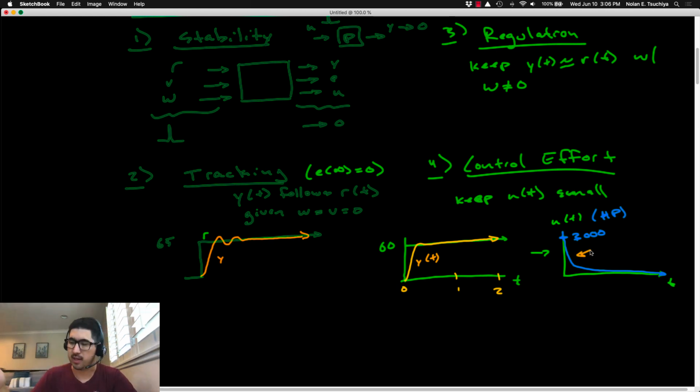In other words, even though theoretically it's possible to design a control system that takes a vehicle from 0 to 60 in under 1 second, the theoretical basis for that would be to provide upwards of 3,000 horsepower for that initial acceleration. Okay, so the point is theoretically things are possible, but in reality, you need to do a reality check. It may not be feasible to implement that controller because, at least, I don't have a vehicle capable of putting that much power to the ground without slipping or breaking something.